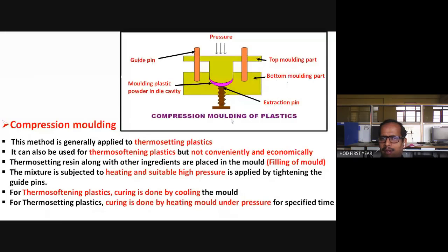Okay, so if it is thermosetting plastic that is undergoing the molding process, here curing is done by what? Keeping the mold as it is under the required temperature, pressure and for a specified time.